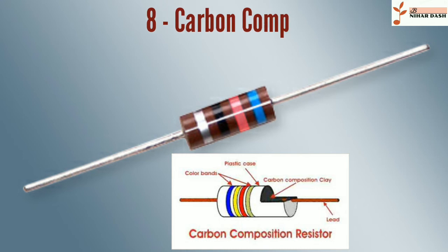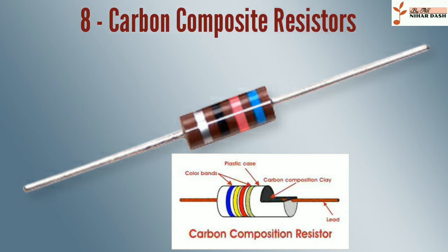Carbon composition old-style dogbone resistors with body, tip, color code marking. Carbon composition resistors in a 1960s valve, vacuum tube, radio. Carbon composition resistors, CCR, consist of a solid cylindrical resistive element with embedded wire leads, or metal end caps to which the lead wires are attached. The body of the resistor is protected with paint or plastic. Early 20th century carbon composition resistors had uninsulated bodies. The lead wires were wrapped around the ends of the resistance element rod and soldered. The completed resistor was painted for color coding of its value.